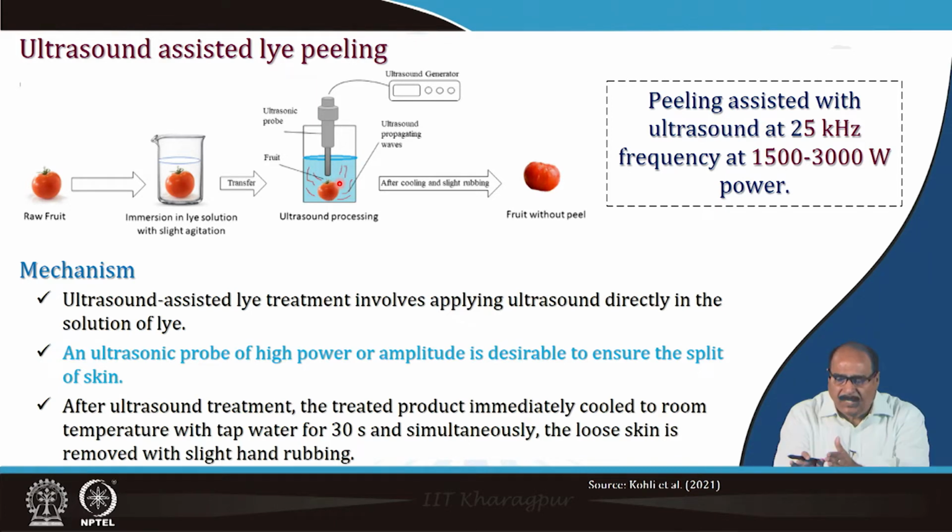So, the remaining process is the same, just that the heating of the lye is replaced with ultrasound at 25 kilohertz frequency at 1500 to 3000 watt power. So, this ultrasound ruptures the skins and tissues and they are easily removed.